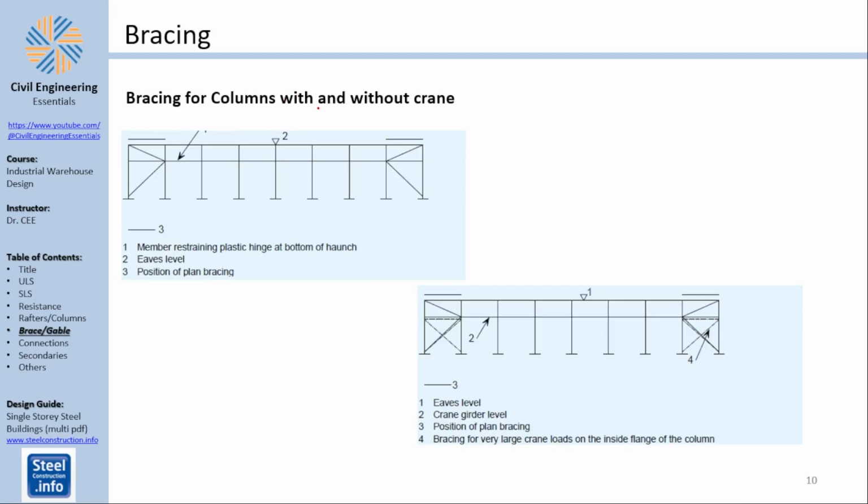Another stabilization that you should take into account is when you have a crane or you have some beam here in the center. Assume you have a crane here. Of course, if a crane moves back and forth and you have some sort of load attached to that crane, like some sort of heavy lifting, then when you start moving you have an acceleration, and when you stop moving you have an acceleration. This will shake the entire warehouse left and right, and you need to provide proper X cross bracing stabilization at the beginning and at the end. And notice it's being connected at the crane girder level. So that is kind of cool.